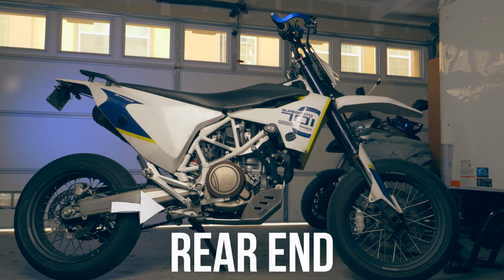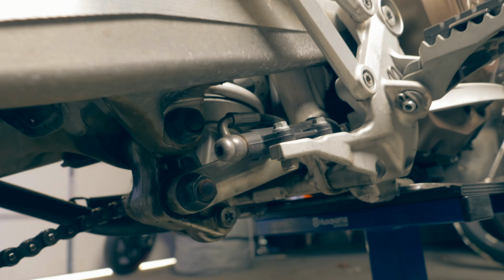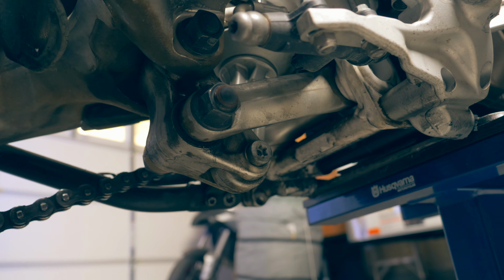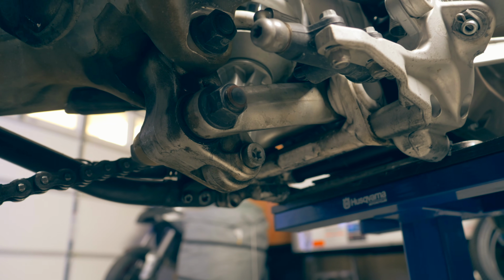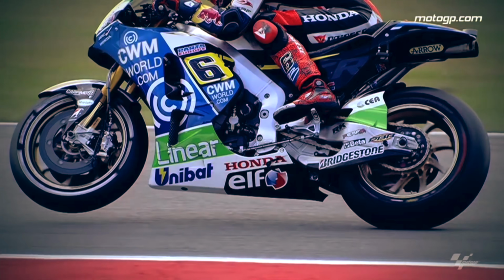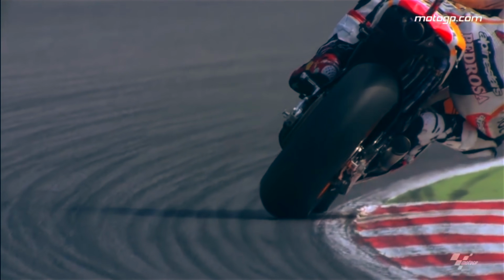What about the way that the shock attaches to the swing arm? This is very important indeed. Most modern motorcycles utilize what is called a rocker arm and linkage suspension with a single shock. This enables progressively stiffer resistance to wheel deflection using a constant rate spring, which combines sensitivity to small bumps with an increase in check for larger ones.